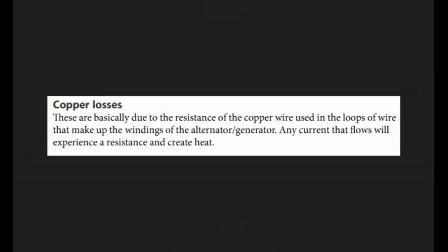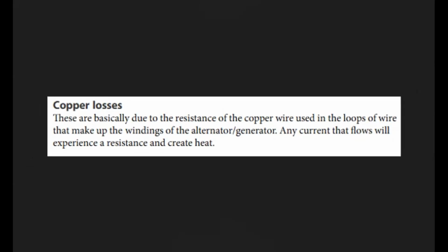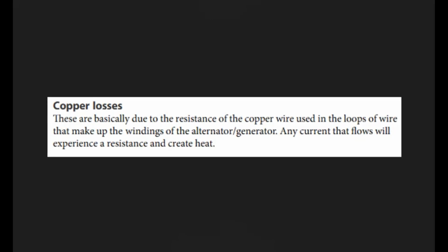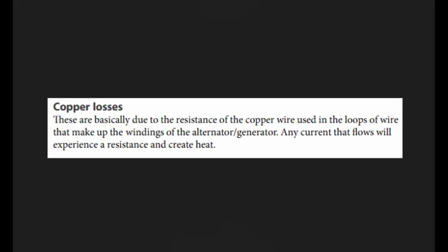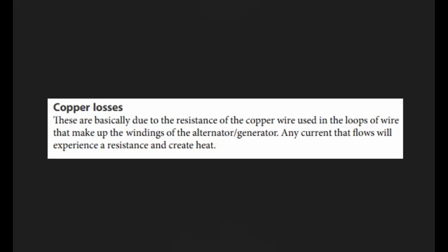Copper losses. These are basically due to heat. The resistance of the copper wire used in loops of wire, they make up the windings of a generator. Any current that flows will experience a resistance that will create heat. Copper losses is exactly heat losses.